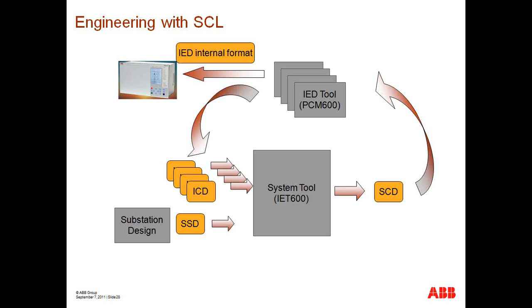the engineering process can be done in a centralized tool, where the different vendors of IEDs can provide their ICD files, or the IED capabilities descriptions. This information is the input to a systems tool. All the configuration related to the substation automation system is performed here.